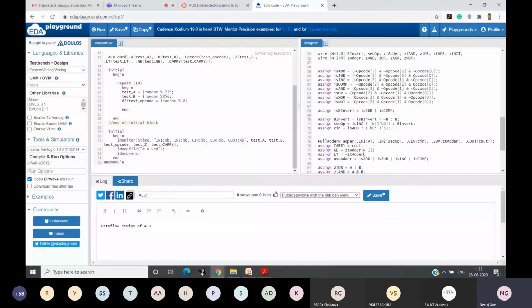So this is essentially catching the sign bit, the MSB of my adder, whether it is high or low. If it is high, that means the value is positive. If it is 1, that means the value is less than.